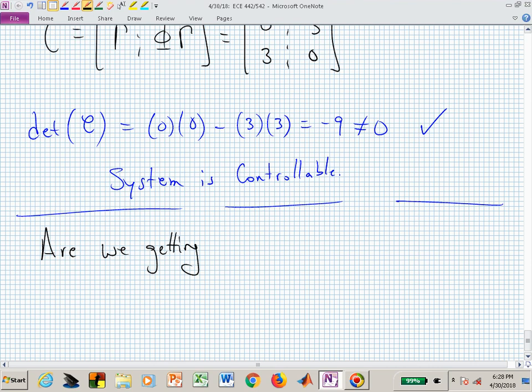That's where our closed loop poles were, and those were not the entire complex z-plane, were they? Those branches, those red lines on the root locus, were just certain locations in the z-plane. Now, if our system is controllable, we can place our closed loop poles wherever we want. We don't have to be restricted to these root locus branches.